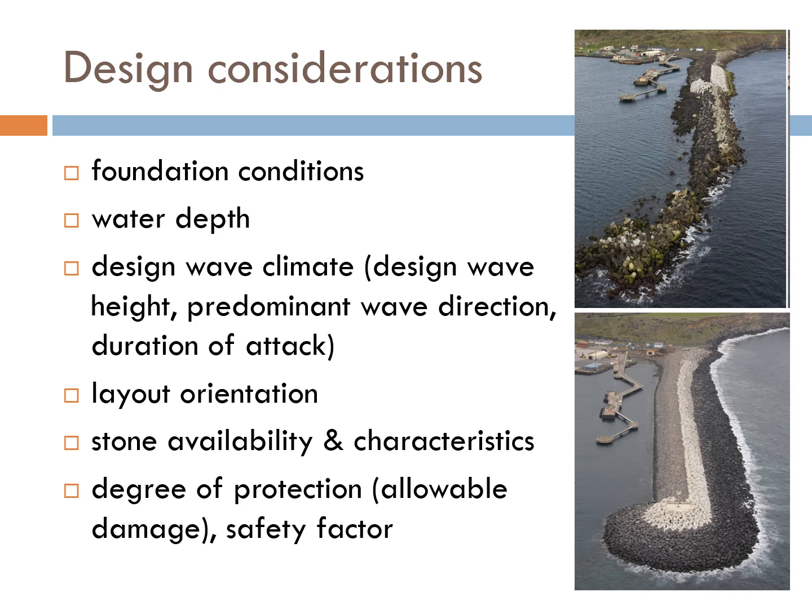On the other hand, if small armor units are used, then the degree of protection is lower and the structure is more prone to damage under storm events. So the concept of allowable damage will be adopted in the design, which will be discussed next, and using appropriate safety factor, the rubble mound armor unit size can then be determined accordingly.